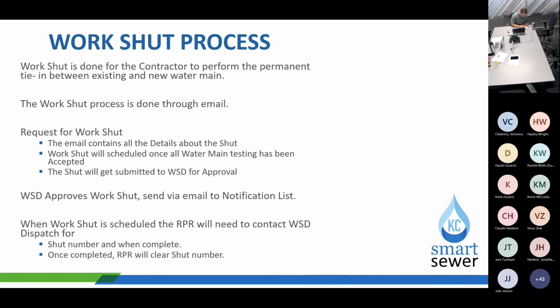The main thing as well, when the work shut is even scheduled, or even before the work shut is scheduled, the water testing will be in. It will be accepted. It will be approved. It will be made aware that this line has no bacteria in it, or it passes all the requirements in order to drink it after it has been tied in.